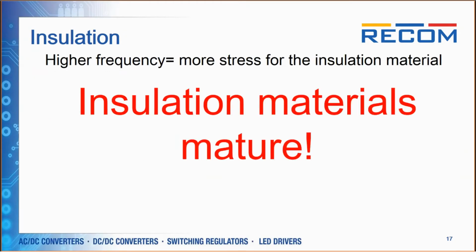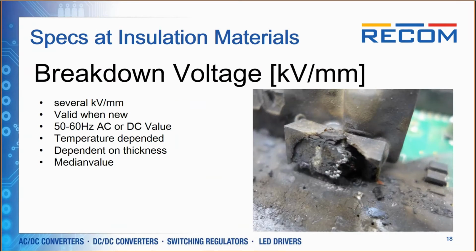So when we look at what is related to the gate drive power supplies and the insulation, we have to say higher frequencies will put more stress on the insulation materials, and this is also not always known. Insulation materials age, so they get worse with time. Let's look a little at the specs of such materials, so that you don't end up with such a picture as on the right hand. One thing is the breakdown voltage you have to consider on insulation materials.